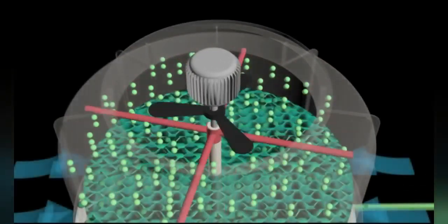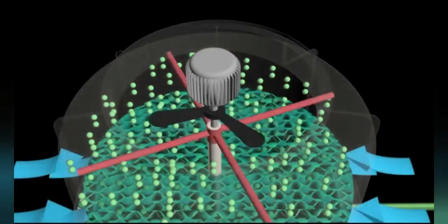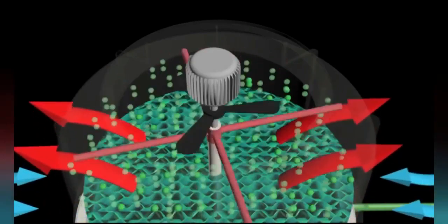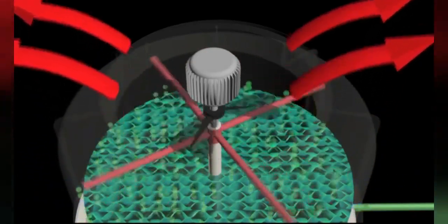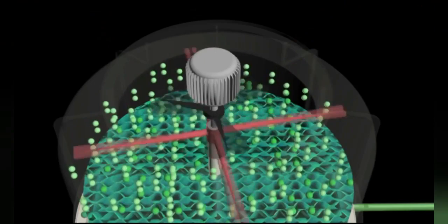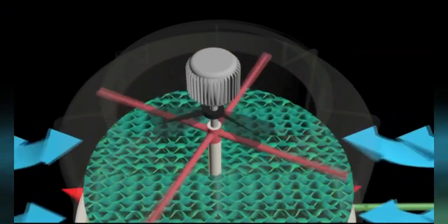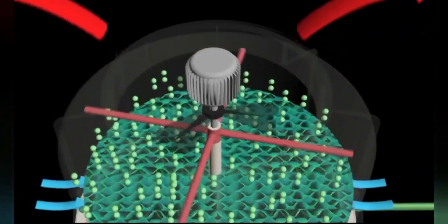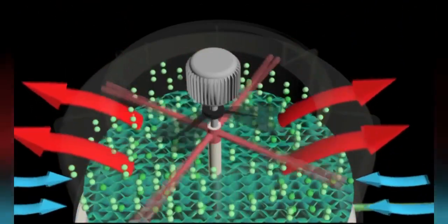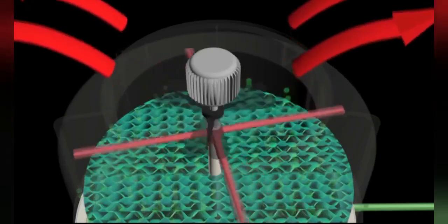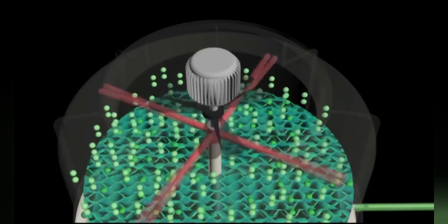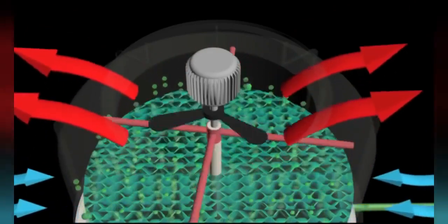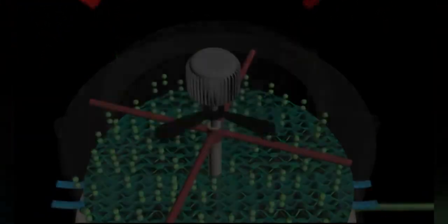Water will gush down through the fins to reduce the speed of water going down. This can delay the time and the heat can be absorbed more effectively by the surrounding air that is passing through the fins. Air through the fins is forced by a rotating fan on the sprinkler blade rotated by the motor. This fan rotates with its gusts upward. This will cause the air to move from the bottom to the top of the cooling tower, where it is opposite to the flow of the condenser water.